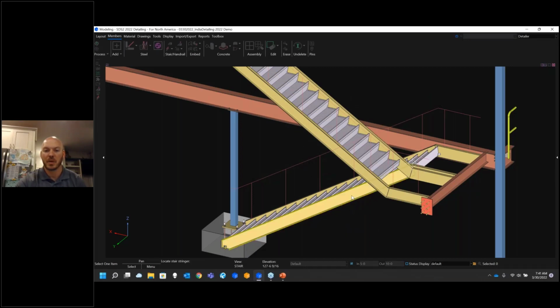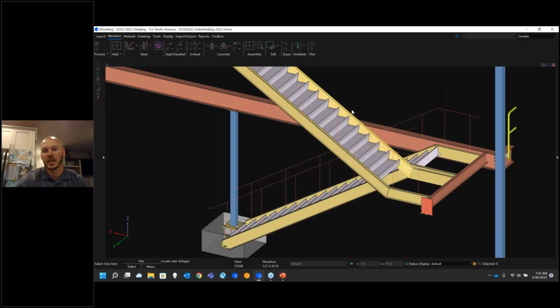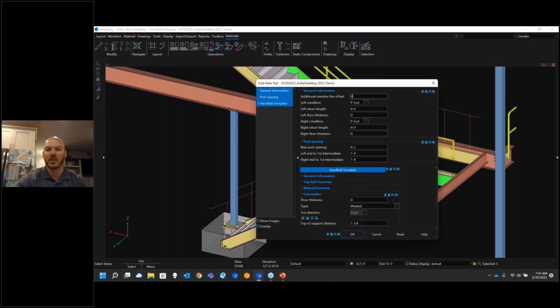Again, for time purposes, I'm not going to do all the stairs. I'll just do these first couple here and make adjustments. So this time I'm on that interior. I don't want that to extend all the way along that return. I just want it to go a little bit so that we make our turn on the interior of this stair tower. And then same thing here on that interior stringer, make my adjustments.